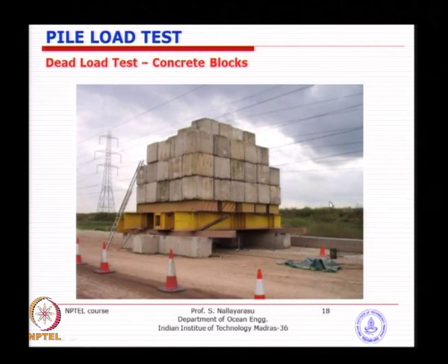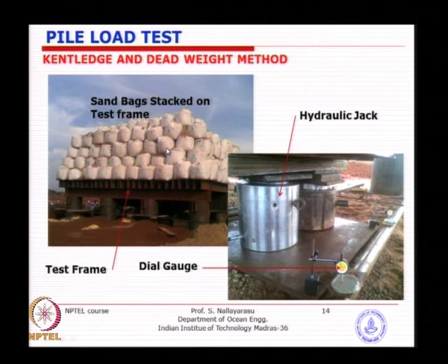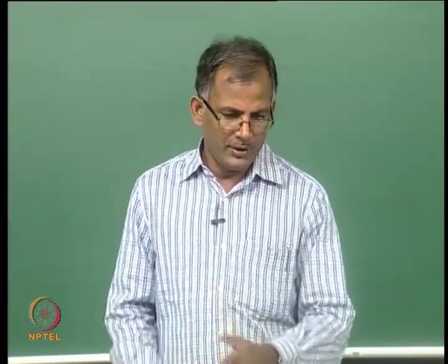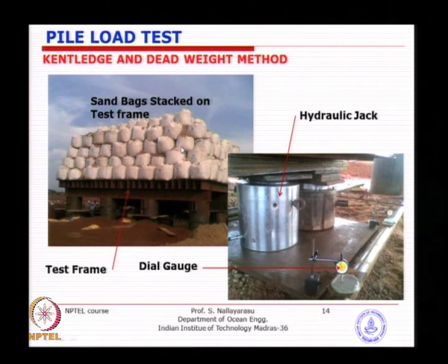Another load test using concrete blocks instead of sandbags. Many times people use this because it is easy to handle and can be used in multiple places, it only requires storage, but in any case in construction sites you will find many of these concrete blocks with spare capacities available there. But many times people use sandbags because they are easy to dispose of, they can be used for construction work, no extra storage space is required, and each one of them will be weighed before placing it on the top, so that you know the weight of it.